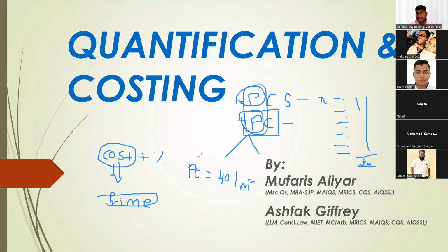Cost of the material means if the contractor wants to go and buy the material from the store, that is his cost. He wants to pay for it. So when the contractor is pricing it, if he sees the PC rate of 40 dirham in the bill of quantities during his pricing of tender, what he will do with this 40 dirham, he will calculate the labor cost of laying the tile, per one tile or per square meter. This is based on the unit in the bill of quantity.